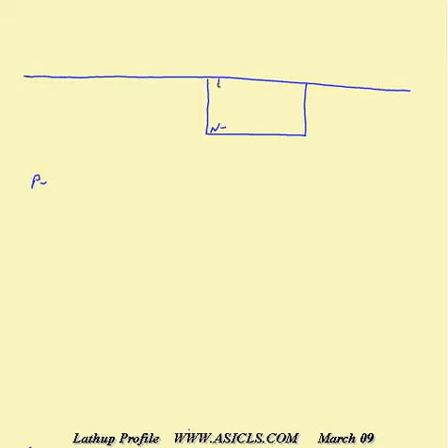Then we show our P-type transistor being formed in the N-well by two P+ implants. P+ indicates highly doped. And of course now we show the gate. We'll mark this drain, gate and source. Next we'll show the N+ implant, also called N-tap, being defined in the N-well. N+ makes good contact to N-, and we'll also show the metallization, which we'll use in a moment, to connect